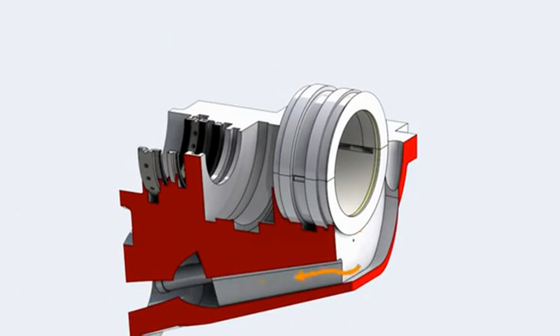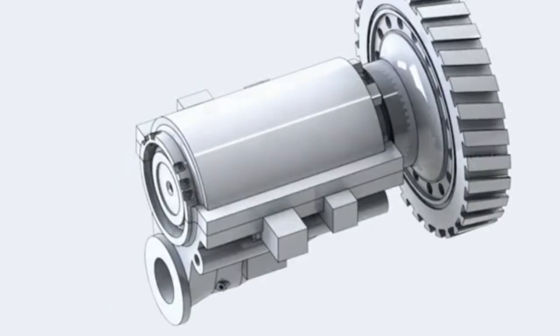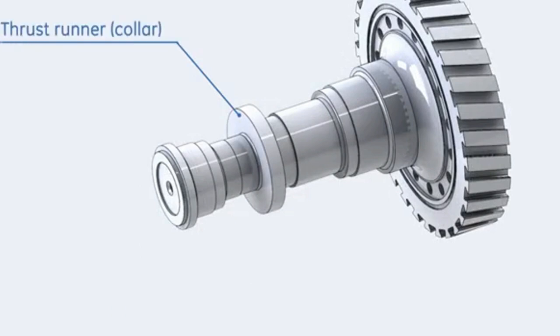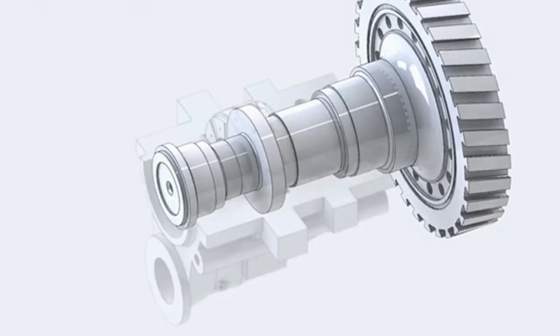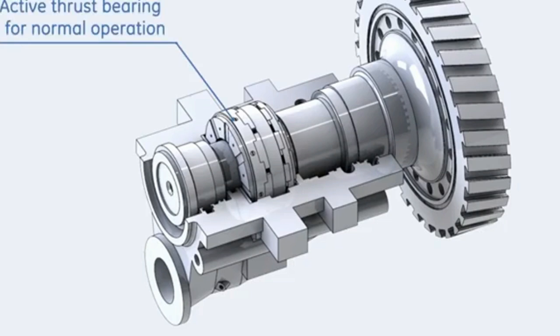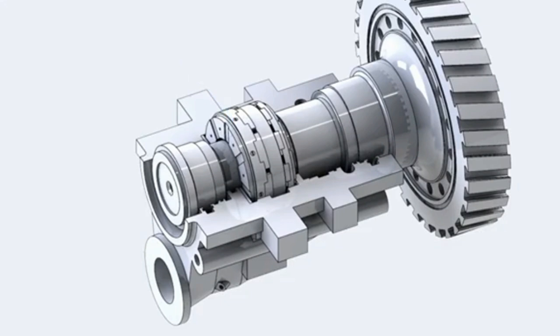The thrust-bearing major components are the thrust runner, which is integrated in the compressor rotor forward stub shaft, and two thrust bearings. During the normal operation of the gas turbine, the sum of axial forces induced by the airflow on the compressor stages and the hot gases flow through the turbine stages tend to move the rotor in the upstream direction, so that the active thrust bearing is located on the forward side of the thrust runner. While in the transient operation during startup and shutdown, the shaft tends to move in the downstream direction, where the inactive or unloaded thrust bearing is located.